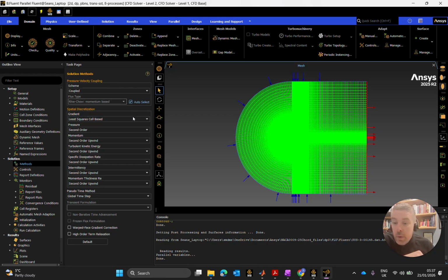And then no one had mentioned anything to do with the spatial discretization, which I was pretty shocked at, as usually some people come in with great ideas on this. The only thing I could have thought that we might have been able to do in this is going for, say, the likes of the Green-Gauss node based. That's the heaviest on computational effort to resolve this, which is to do with the convection terms, I believe. But you need a very structured mesh for that, which we do. But changing things in here, I would really reserve that for three-dimensional analysis.